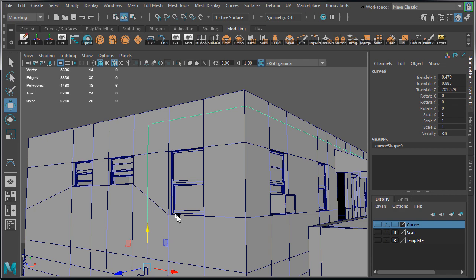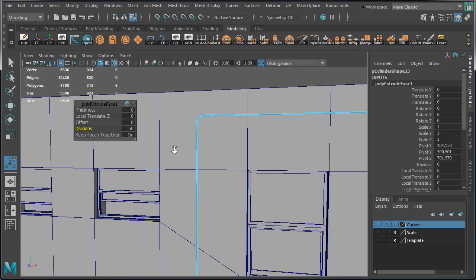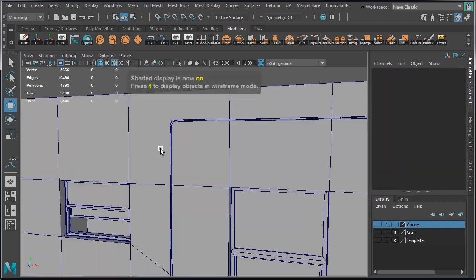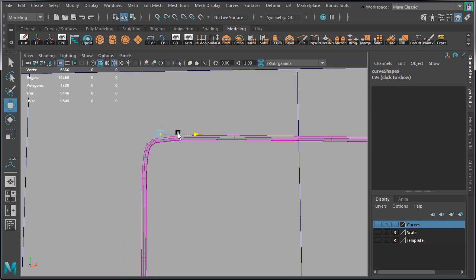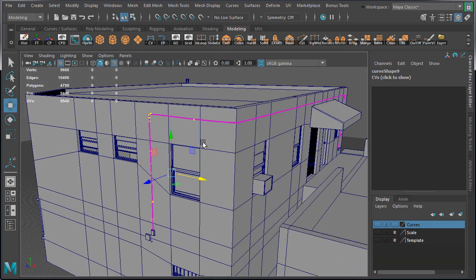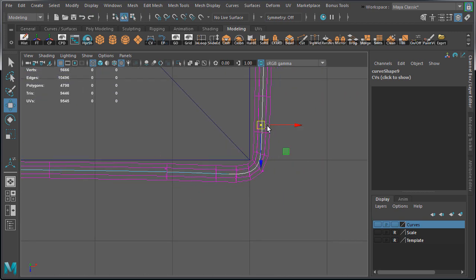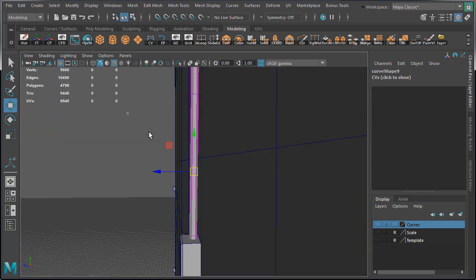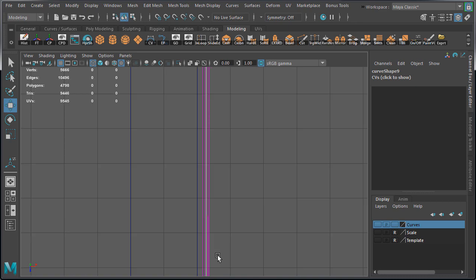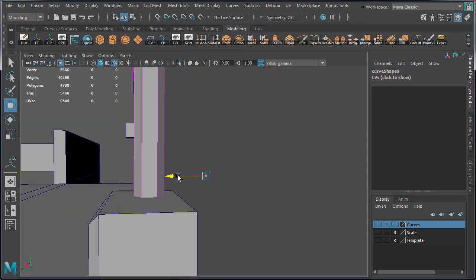When I extruded along this long curve, I had to manually input the divisions and bump it up to 55, just to make sure there was enough geometry to create the wire shape. So again, focus on modeling first and optimizing later. After you extrude along the curve, you will almost always have to come back, modify and adjust the control vertices of the curve to update your wire shape.